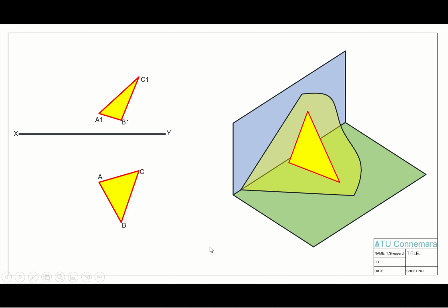This method is going to begin in a very similar way to method 2, insofar as we're going to first of all find what's known as a strike line, or a line on our lamina that is going to be parallel to the horizontal trace. If you remember from our previous example, we were using this idea of raising a level of water to find a watermark on our lamina. That's our strike line. So to do that, we draw a line. That watermark line will appear parallel to our horizontal trace, which we know is going to be a level line in our elevation.